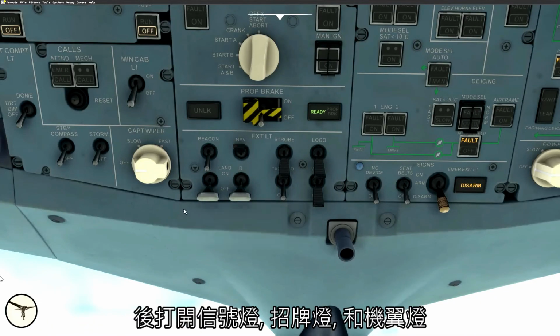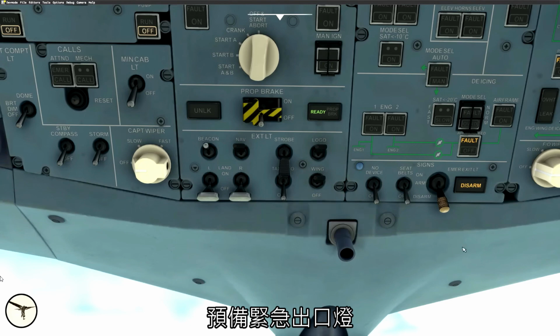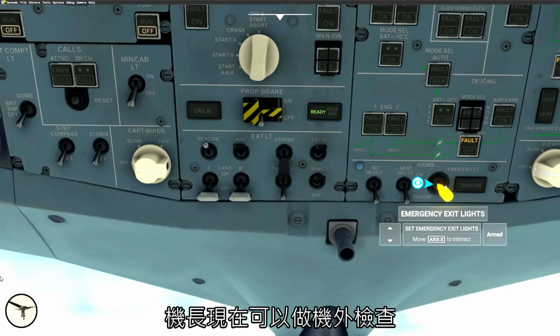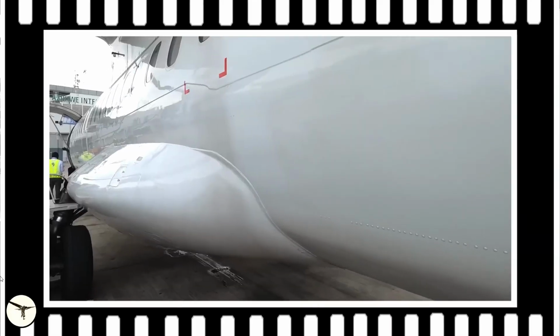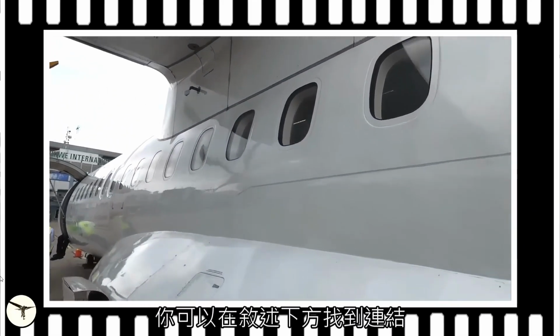Finally, select beacon, logo, and wing lights on. The other lights need AC wide power, so they remain off. Select emergency exit lights to arm. The captain will now do the external inspection. I have made a video about that. You can find a link in the description below.